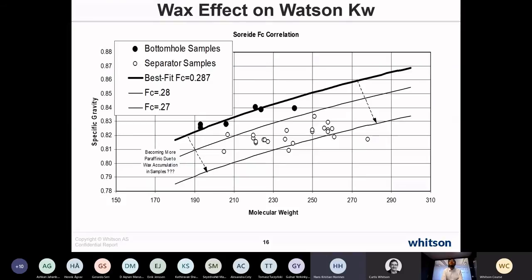Yeah, because the one problem you may end up getting by heating the separator gas sample is that if there is some kind of liquid carryover with the gas in the sample that you have collected, it will be in equilibrium at 12 degrees C, at the separator temperature.